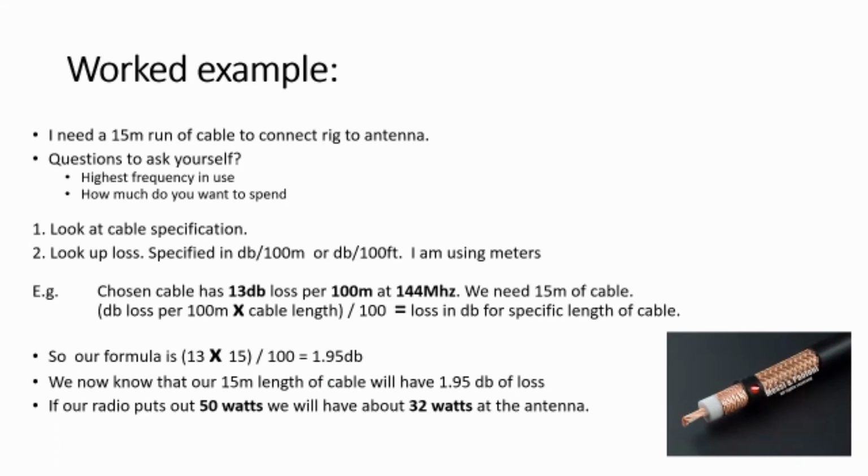So for example, you need a 15-meter run of cable to connect a rig to the antenna. The first question you need to ask yourself is, what's the highest frequency I'm going to use? Is it HF? Is it 2 meters? Is it 70 cm, 23 cm? Or maybe you're trying to get onto QO-100. Is it 2.4 gigahertz? The second question is, how much do you want to spend? Because you can spend a lot of money on cables, especially when you get into the specialized stuff.